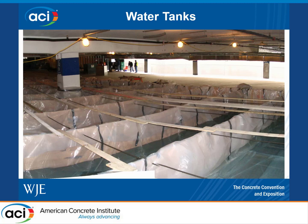And again, you can see, like in this case, this was at an airport parking garage that we were testing. I believe we had 38 inches of water over a very large area, so a very large volume of water that we had to pump out at the end of the test. So we also planned out how much capacity our pumps would have, how many pumps we would need, what drain lines we were sending the water to, all in advance, so we didn't overload their system.